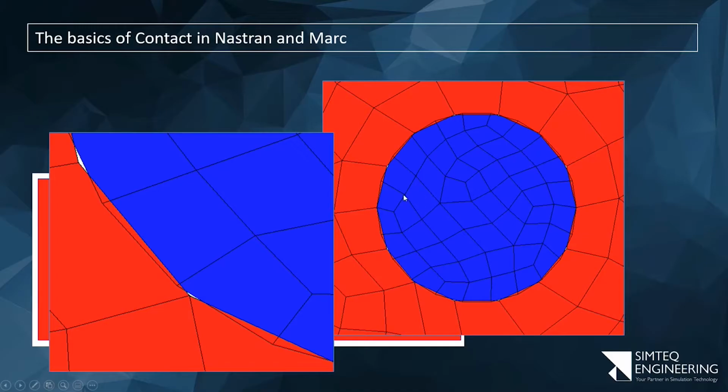Now, that doesn't work that well. If I try to do it, I'll see my overlaps reduce. It's not such large overlaps anymore, and I don't have such large gaps, but the problem doesn't disappear. Bear in mind that a couple of microns interference fit can cause really severe stresses. Some interference fits are of the order of 10 microns. So a 10 micron error in overlap or gap will cause utterly wrong answers.